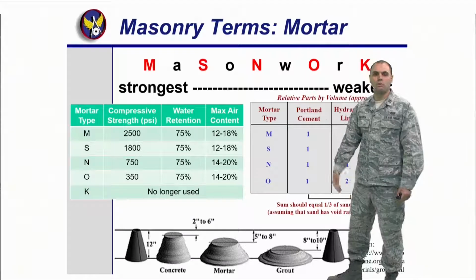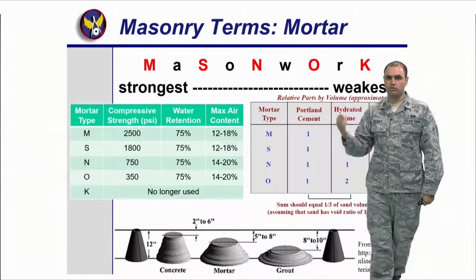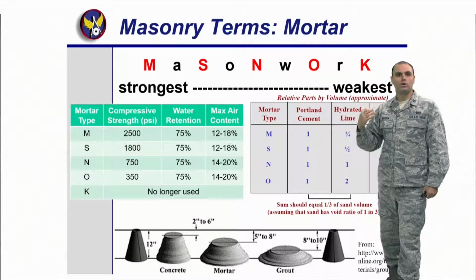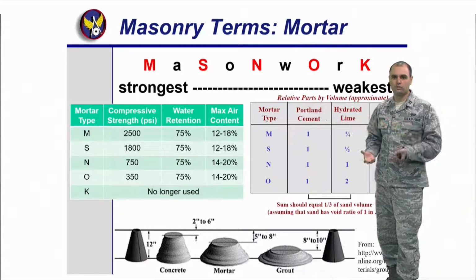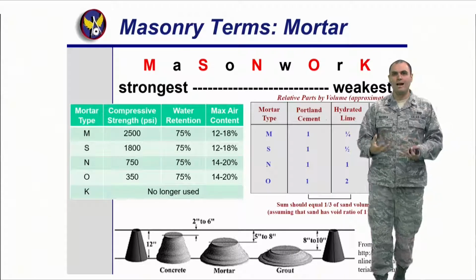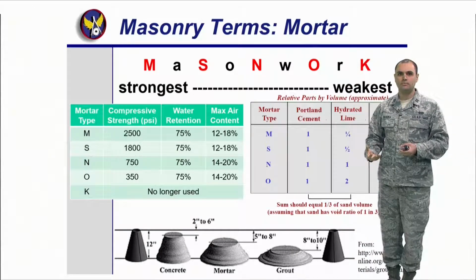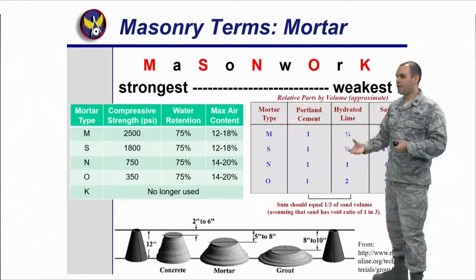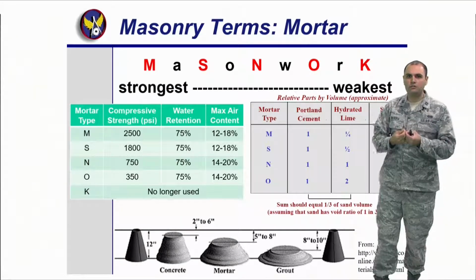And what is grout? Well, grout is how we're going to, let's just say you calculate it and you need some flexural strength because your wall may topple or your lintel or your column, then you're going to fill some of the holes with grout, all right? But as you can see, grout is very, very, very watery. Why, right? Very high slump. Why is it very, very high slump? Because when you pick up a CMU, you're going to see that it has a lot of little voids, right?